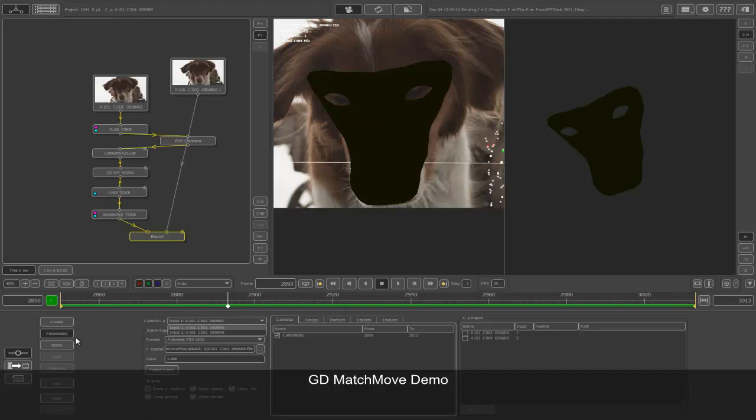So once I have an input, I can choose whatever I want. Once it's chosen, just make sure you set the proper file format here. By a lot of trial and error, we have found that Maya output over here does not actually work. When we save the file for Maya, when we open it up over there, it absolutely is a total waste of time. It does nothing. So better option is save it out as FBX, and once you open it in Maya, we can actually get started up.